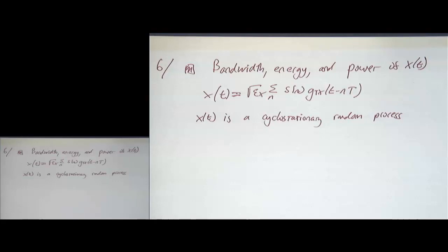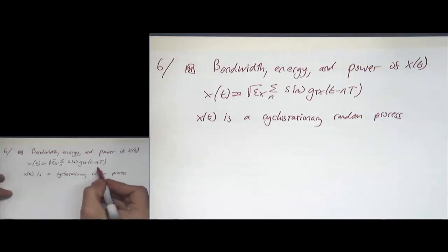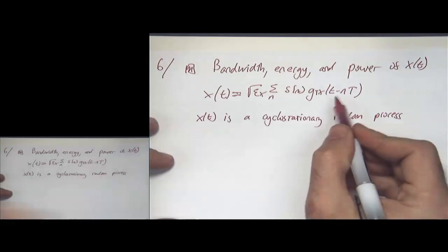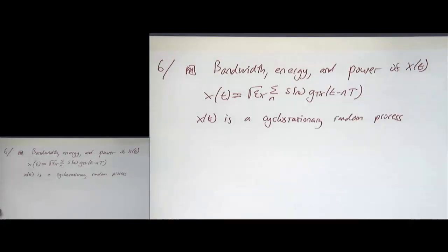let's say, a government agency that was listening to spectrum and trying to determine if there was a digital cellular signal in that spectrum. If you know that wireless signals are generated according to this process here, then they'll have some sort of cyclostationary statistics that you could then use to estimate. You could actually estimate the symbol period and other things here. So anyways, there's application of this. What it means is that we can't really compute the power spectrum in a straightforward way.